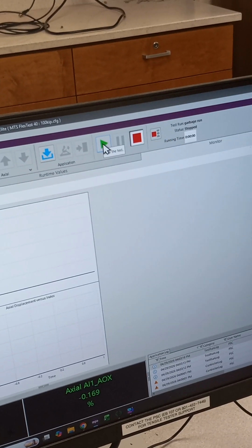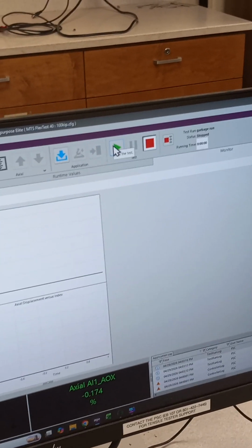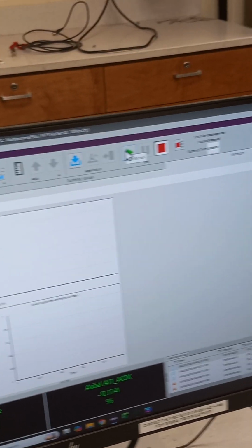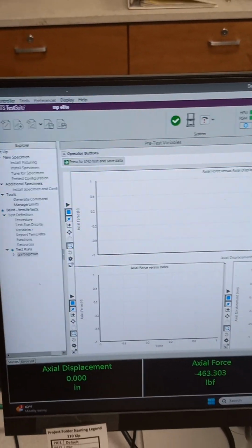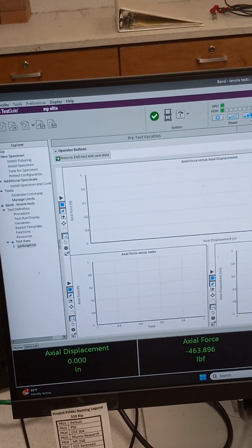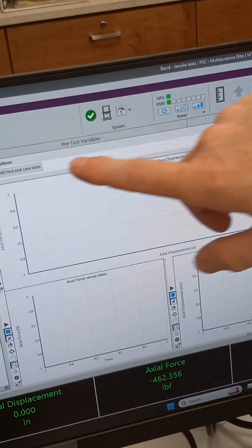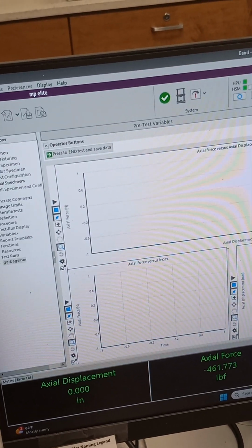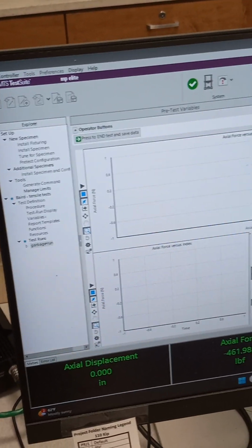So this red square is kind of your pseudo e-stop. If you hit that button, it will stop the test wherever it's at. You remember that flow diagram that it was following? It will stop wherever it's at, and it won't continue. If you click this button, that's the user info button that we told it to add. If you hit that one, it will jump out of that parallel loop and go down and save your data and end the test normally. So this is how you would end the test normally early. If something bad is happening, please go ahead and hit that. We don't care whether it saves the data or not. So those are the differences between those two.